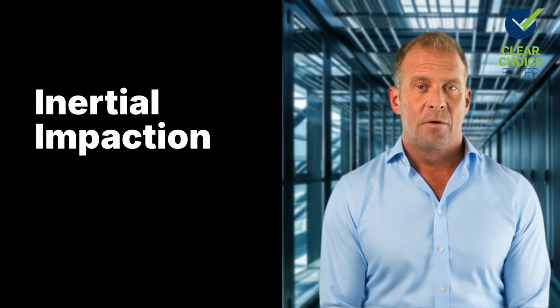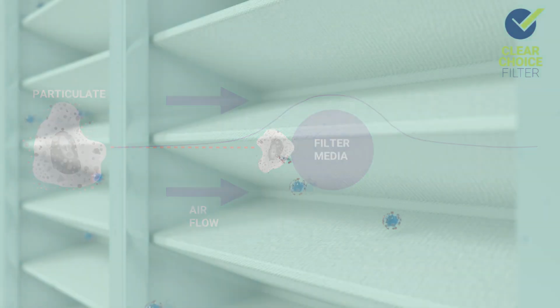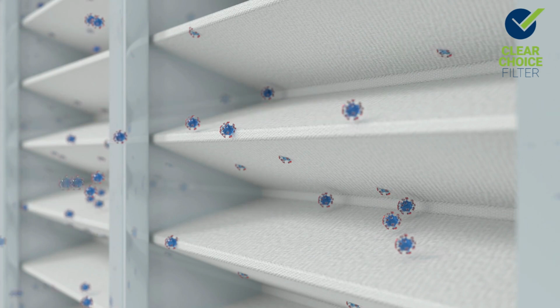The next mechanism we will discuss is inertial impaction. Inertial impaction occurs when particles traveling in a fluid stream cannot follow the curvature of the airflow due to their inertia. As a result, they collide with and adhere to the fibers or surface of the filter media. This mechanism is particularly effective for larger, heavier particles and is widely used in air filtration applications such as HVAC systems and industrial air cleaners.